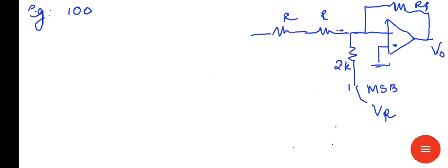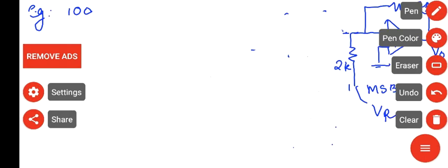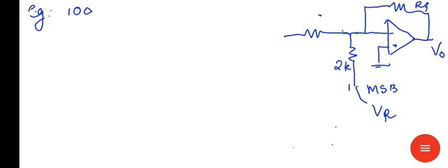So this is R and one end is grounded. Again this R and R in series is 2R. Replace it by 2R. This end is grounded. So at last we got one 2R resistance to ground and another 2R resistance that is connected to VR.